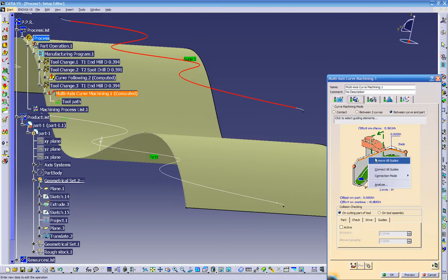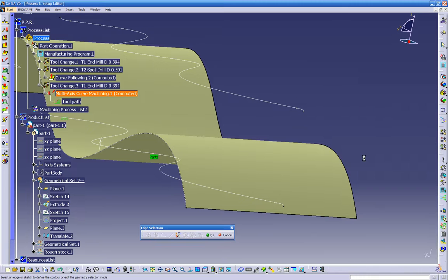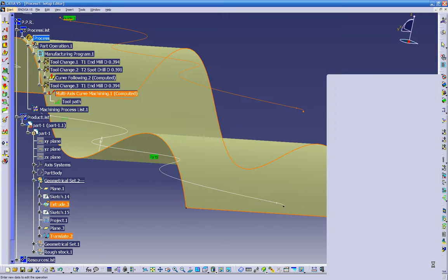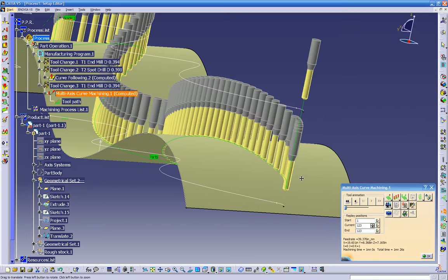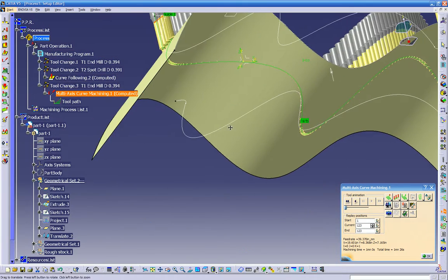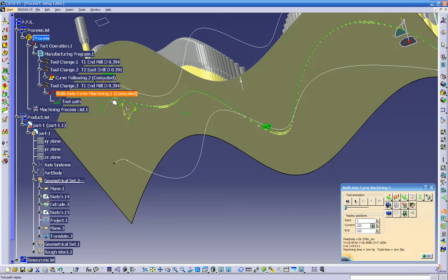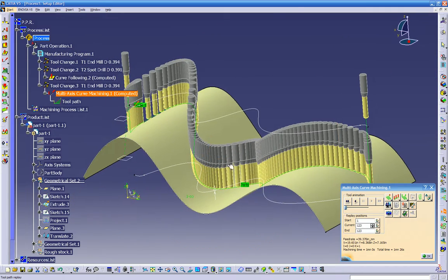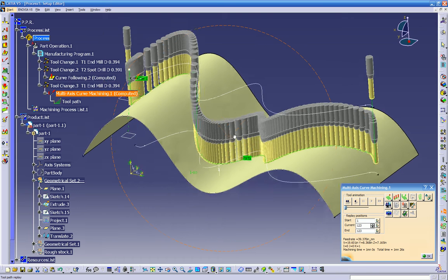So if you right click, remove, now it becomes all red, it's ready to be picked. And let's click back on the sketch, toolpath replay. See, now we have the lead in, but the tool doesn't gouge into the part. And we have a lead out, so whatever you created, that's all it's going to be.